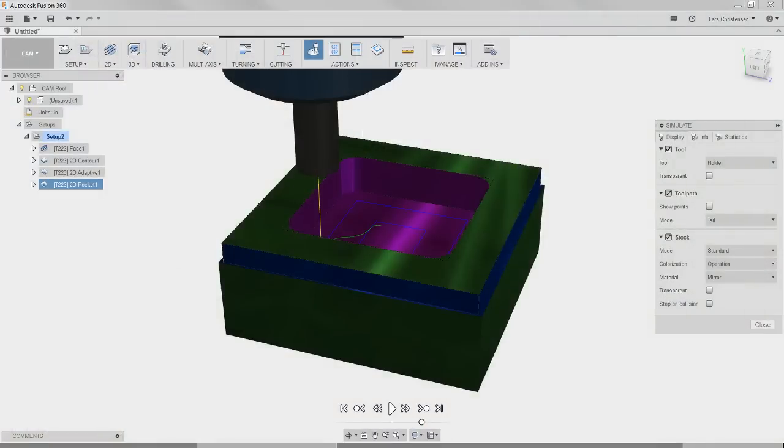That can give you, you know, if those things are in order, you picked up right. If some of those things are not in order, something is wrong. And it might be the way you picked up the part out there, how your work offset is set. So also, of course, make sure that you check your machining manual. Now, let's go and take a look at the post, because this is maybe where some of you would like to dig in and get a little bit deeper into this.